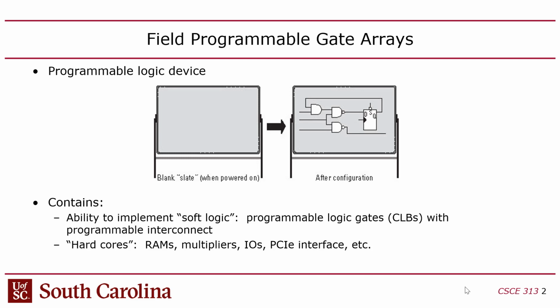And in fact, these boards that we're using in class do exactly that, because when you first power it up, it configures the FPGA from a configuration stored in SRAM, and that's why it's blinking like this. All of this behavior going on right now is actually being driven by the FPGA, and it was configured from a non-volatile RAM that's not on the chip, it's on the board, but it still configures the FPGA. Now you can change that, by the way. You can reprogram that chip on here if you want this thing to do something else when you power it on. Does that make sense?